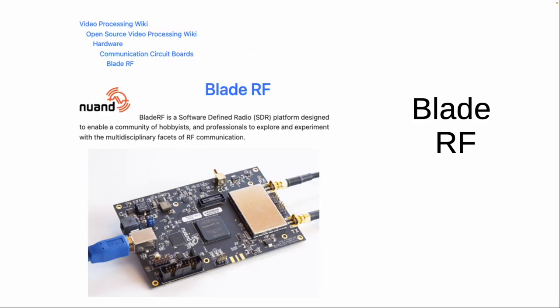I think the BladeRF is interesting. So this actually, the core RTL is based on VHDL. And so historically everybody's been moving to Verilog. It's maybe because it's easier, but the problem is Verilog is dynamically bound, and a lot of VHDL has static binding, so VHDL checks a lot of the errors.